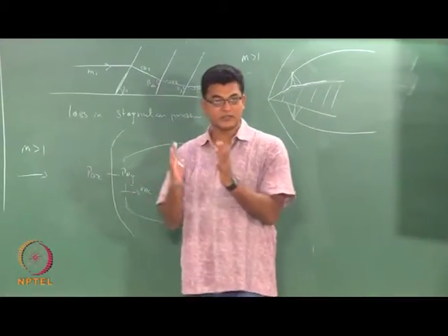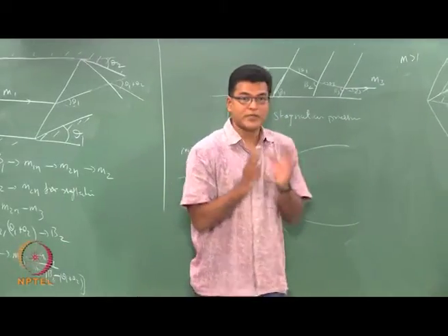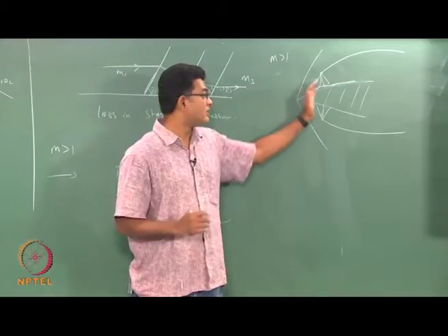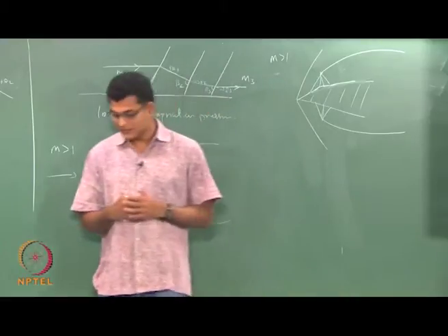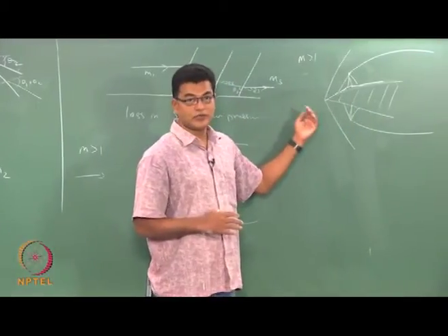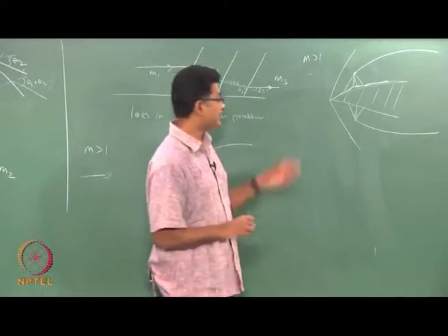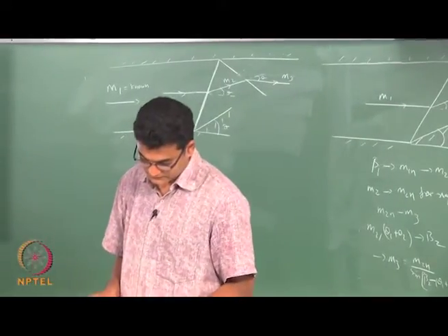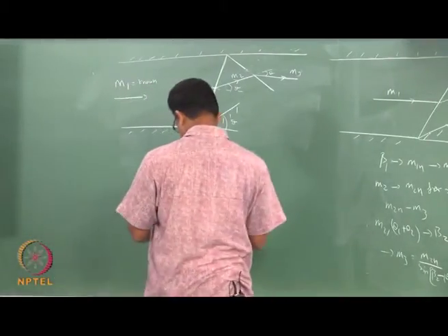So, P0 is the total pressure, it is an indication of how much work it can do. So, you want to maximize that and you want to gain compression inside the diffuser as much as possible. Now, in a compression shock wave you are actually compressing, you are increasing your pressure. So, you want to gain that, you want to do that here, yet you do not want to lose your P0x or the stagnation pressure. So, you can do that in a numerical problem here. So, let us try to work it out.